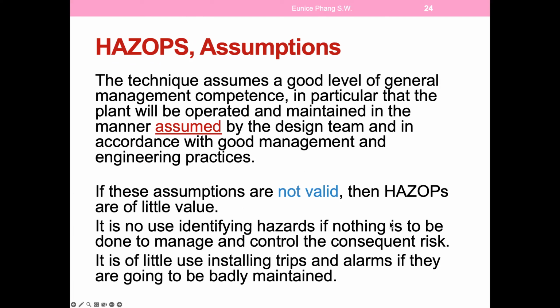Okay, and in HAZOP, because it's a brainstorming exercise, it always has assumptions. But when we make assumptions, we have to assume something that is logical and practical. If the assumptions are not valid, then your HAZOP has no meaning. Also, in HAZOP analysis, even though sometimes we may say the potential causes are natural disasters like earthquakes, volcano eruptions or tsunamis, we can't take any actions to prevent those because we can't prevent natural disasters.